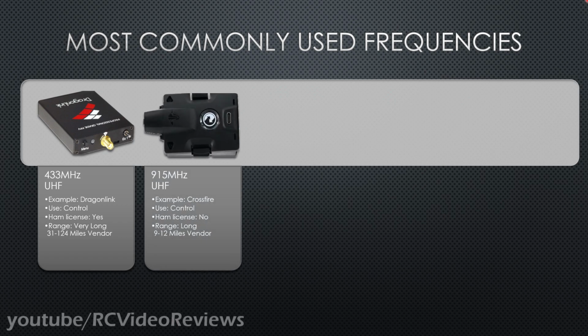Next up is 915 or 868 megahertz. 915 is region 2, which is basically the US. 868 is region 1, which is basically not the US. This is a UHF frequency. One example of a product using 915 megahertz is the Crossfire. Its primary use is control. A ham license is not required for this device because it is Part 15 certified and its range is long. The vendor claims 9 to 12 miles of range on this particular device.